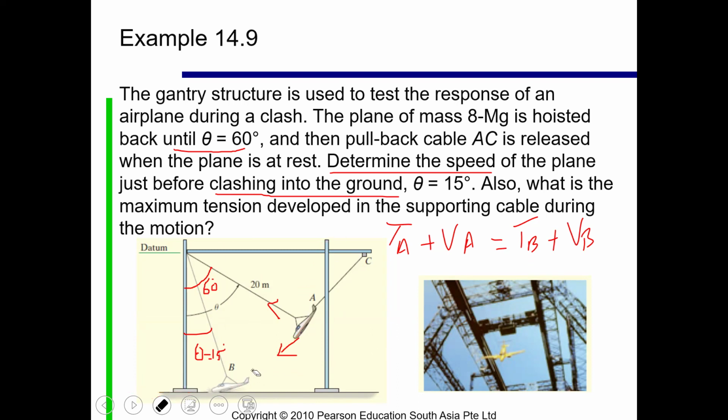Okay. Then what I will do, I am going to consider, for example, the free body diagram of the plane. So the free body diagram of the plane will look something like this. Think of the weight; this is where the tension is present, right? And this is the normal axis and the tangential axis is here. And students, think of the weight acting downward like this, right?